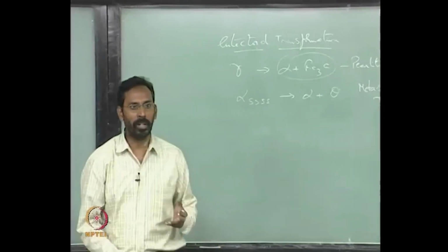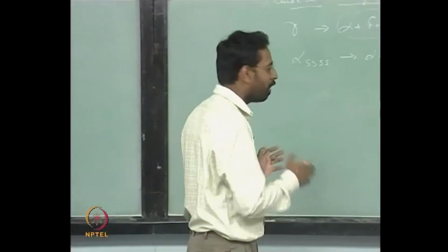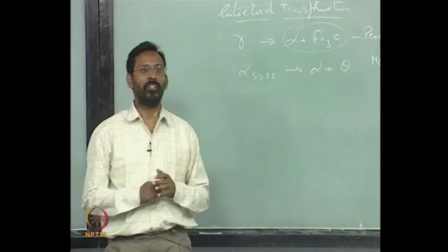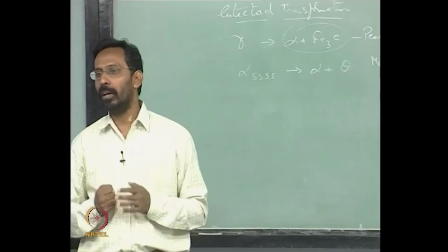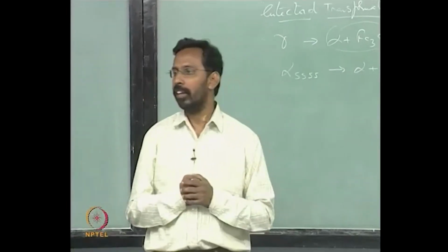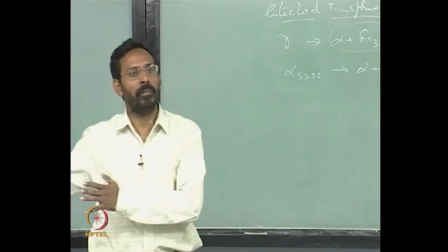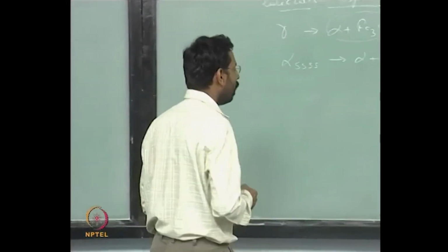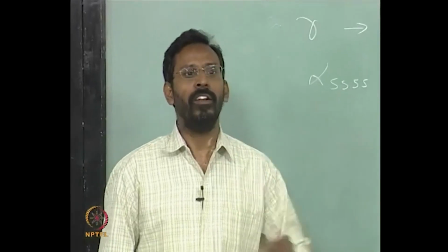So thermodynamics without a kinetics knowledge will not give you any information about the whole phase transformations, because the phase transformation is always a combination of the two. Okay, many times thermodynamics may say yes, this phase will form, but the phase may not form. But at the same time, one important thing that thermodynamics tells us is that if it tells that a phase cannot form, okay, kinetics cannot make it form. Okay, so this is important. For example, if you are at a temperature let us say below the melting point, a solid will not become a liquid.